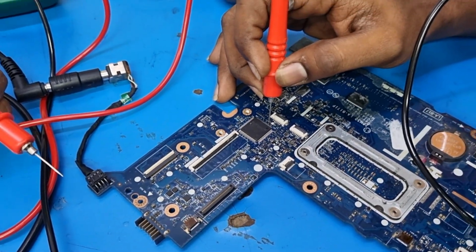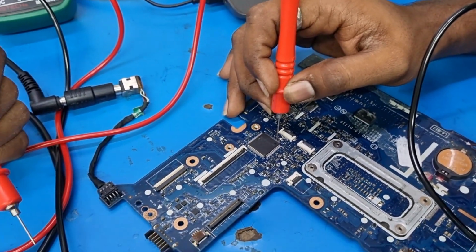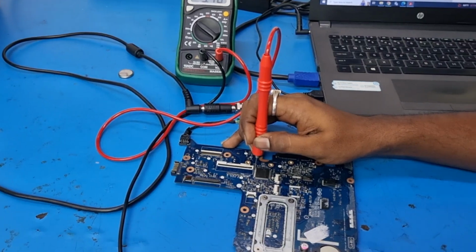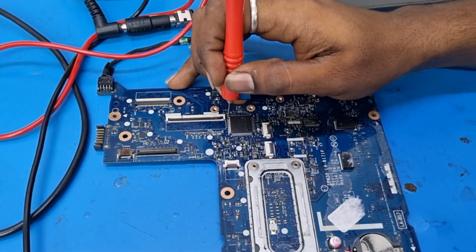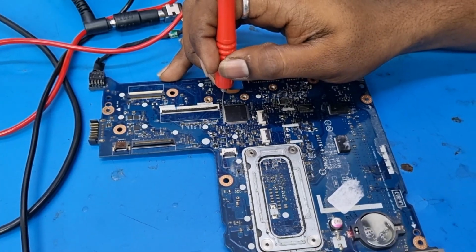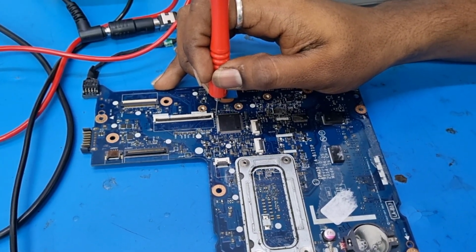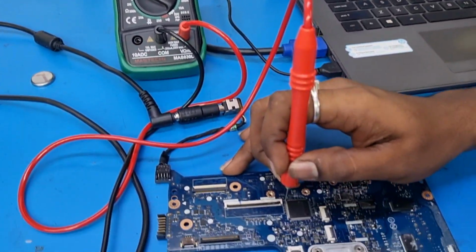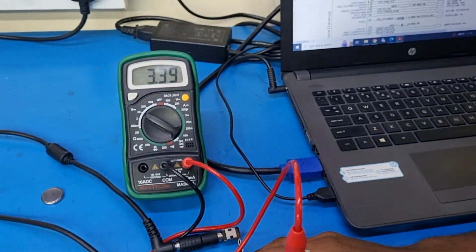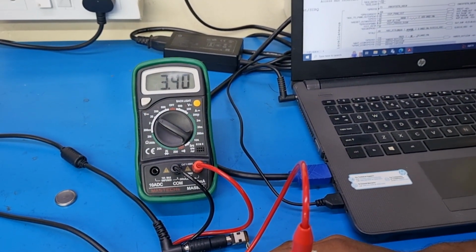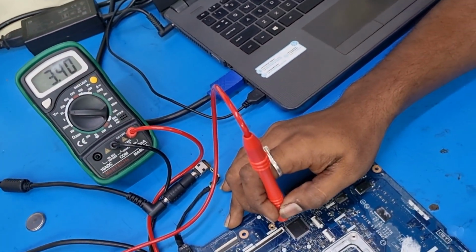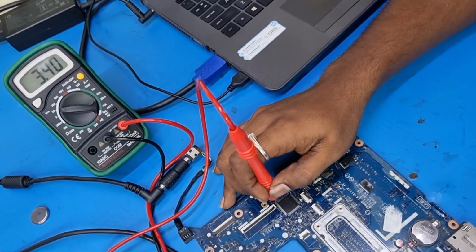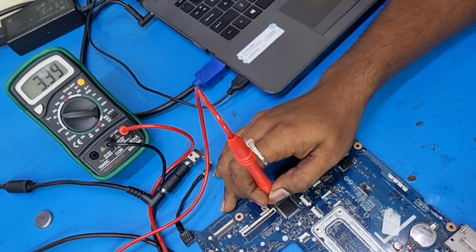Now in the same way we'll see the output. So we are going to connect the output on off button, and that output signal is going to the CPU or the PCH, that is the PM power button, and there will be 3 volt. You can see here 3 volt is showing, and when we press the input power button, at that time this 3 volt goes to 0 and comes back to 3. That means a 3-0-3 variation will be there. In short, when we press the input power button, the 3 volt at the PM power button, or the output power button, goes to 0 and comes back to 3.